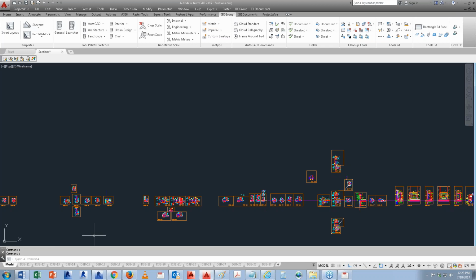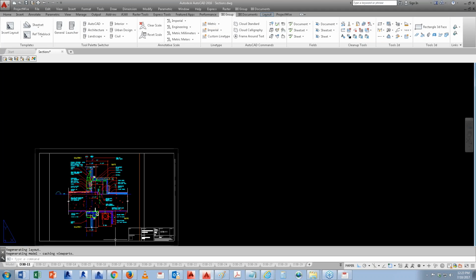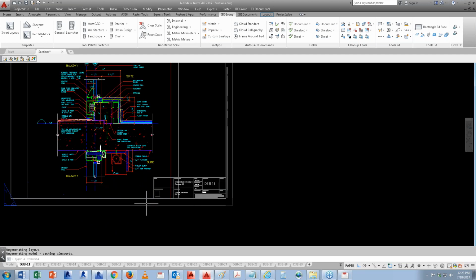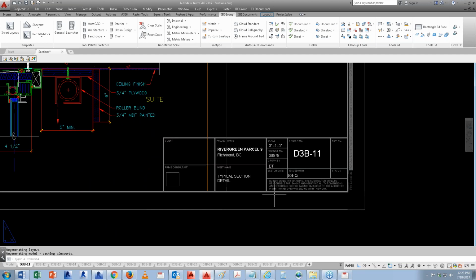Okay. Normally, if you were to replace all your title block 11 by 17, it's going to take you forever. So this is why I said it's better if you just rename it and replace it with that and then call it a day. All right. So now you have this title block. Now what you want is to basically copy, let's say, logos and all the content from the new title block, right?